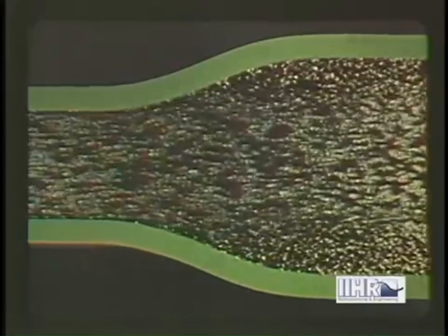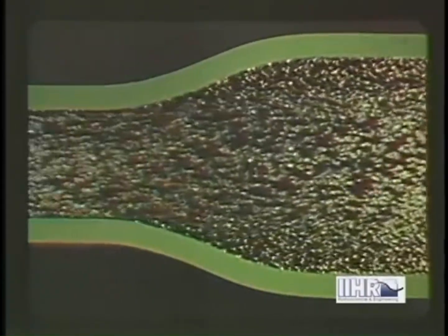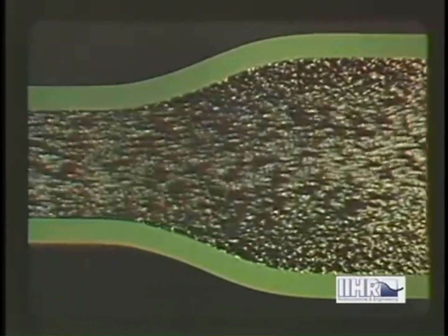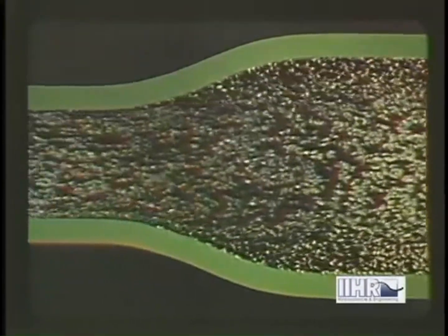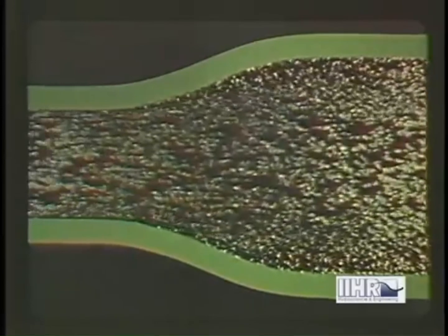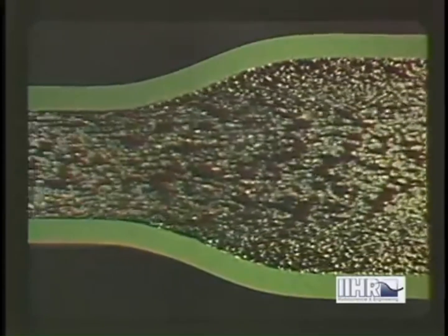Separation leads to 3 important occurrences. First, it changes the anticipated flow pattern. For instance, this channel expansion obviously does not cause the flow itself to expand as rapidly as desired. Secondly, it produces boundary drag, thereby expending energy through the generation of eddies, which rapidly transform to turbulence.